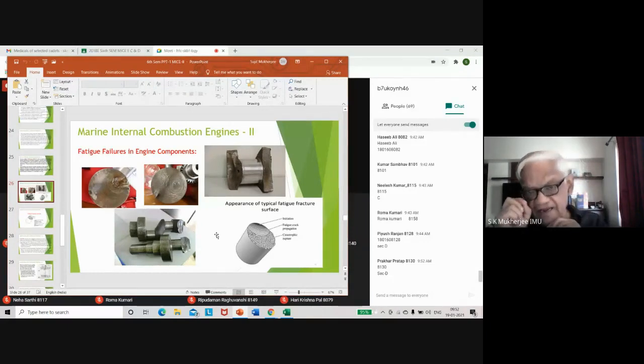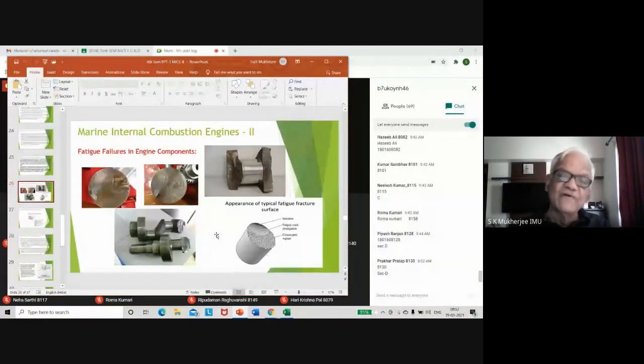There may be an inherent flaw inside the shaft, something like if there is an impurity, if there is an internal fracture on account of stressing. You see, sometimes the shaft has got internal stresses, and that stress has caused the crystalline structure to separate. Even if one crystalline structure element separates, it will become a cascading effect, one after another, one after another. That is called a cascading effect, and the crack will keep expanding. So that's how fatigue failure starts.